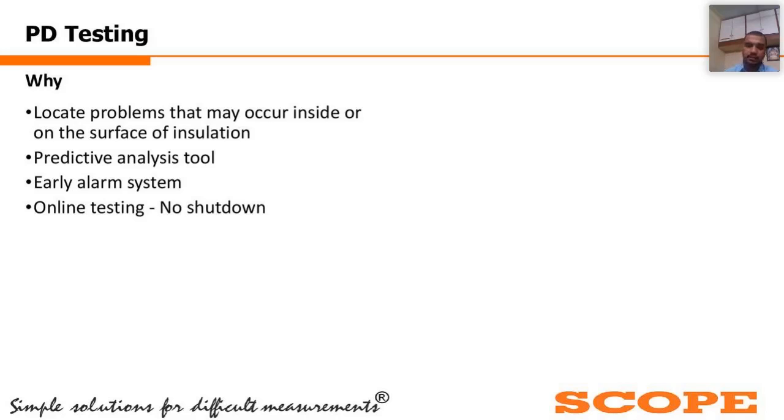By predictive analysis, what we mean to say is, suppose a defect is detected. We have already detected it. We know some partial discharge is happening. Let's say some corona is happening, or some void kind of discharge is happening over there. Now, due to one reason or another, because it is not actually very feasible for us at the substation to take the shutdown more often than not, what we do is we put that particular area of the insulation or that particular case in our monitoring system.